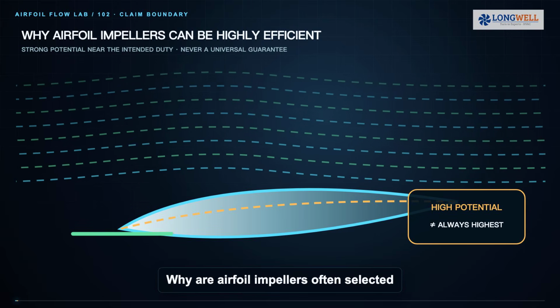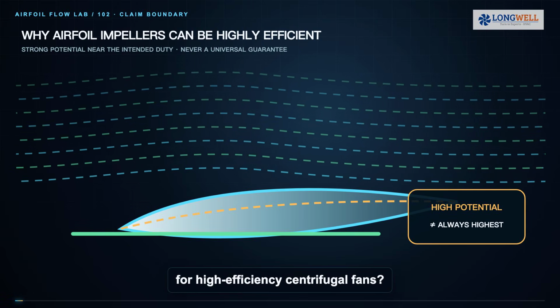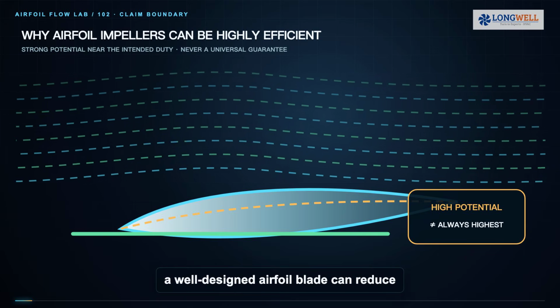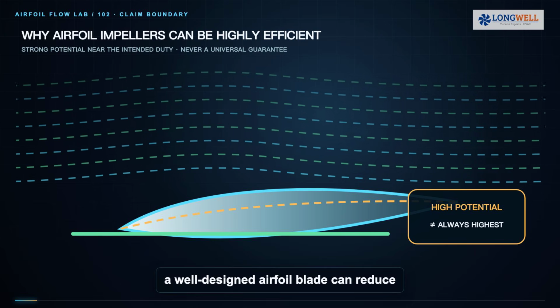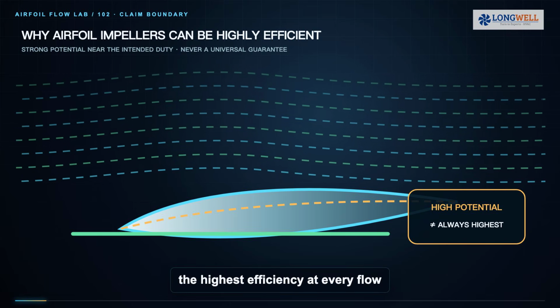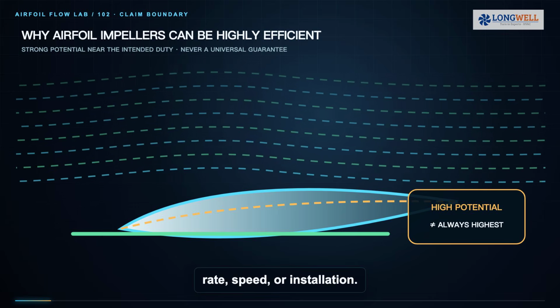Why are airfoil impellers often selected for high-efficiency centrifugal fans? Near the intended duty point, a well-designed airfoil blade can reduce aerodynamic loss. But an airfoil label never guarantees the highest efficiency at every flow rate, speed, or installation.